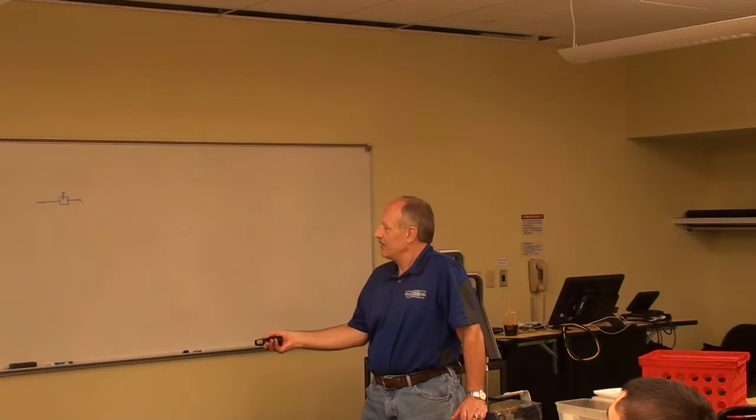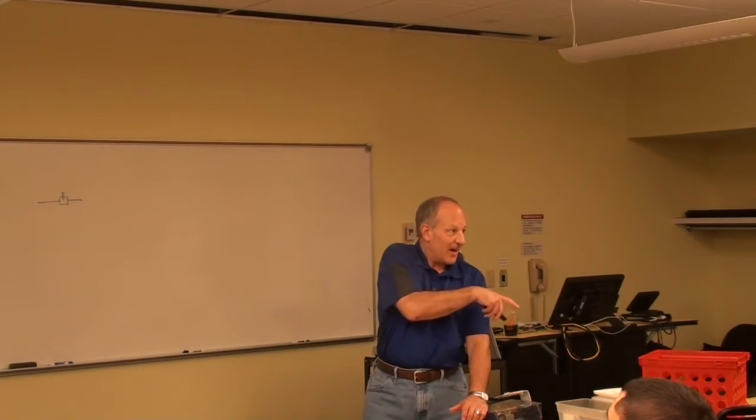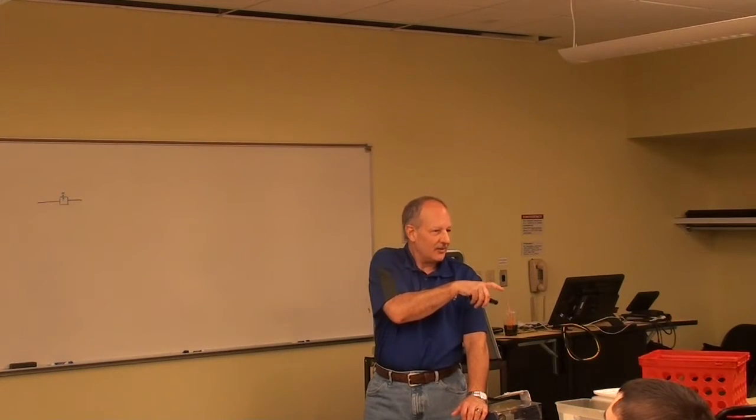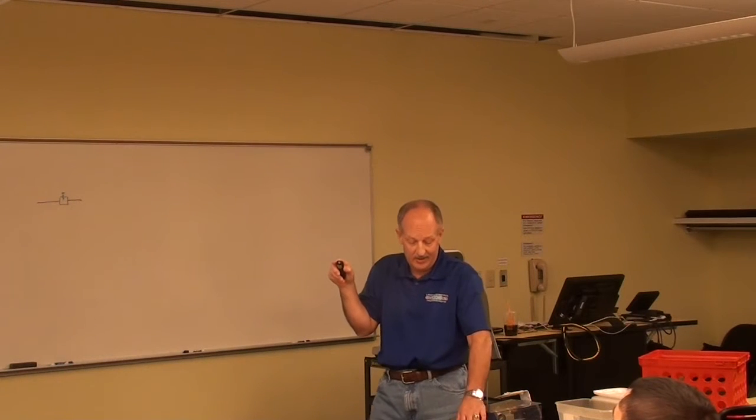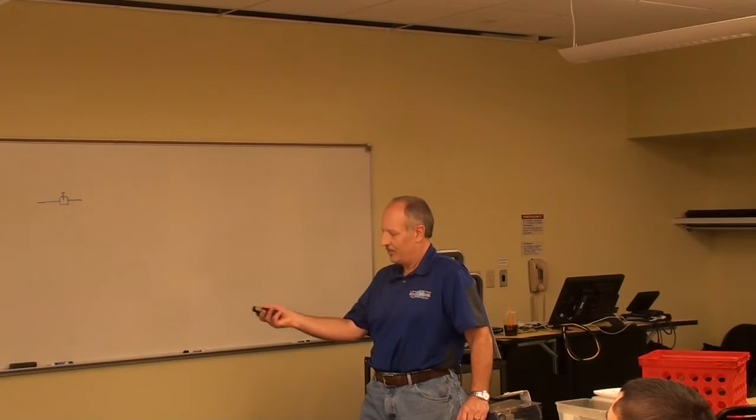Solenoid valves, last year was 1/8" port diameter. If you remember from my presentation, we had this big discussion about CV ratings. That used to be how they would qualify solenoid valves, by the CV rating, which is basically a measure of how much flow you can get through the ports. They got rid of that, and now they made it simple and just say maximum 1/8". I think these are 3/8, or 1/4 inch, sorry.